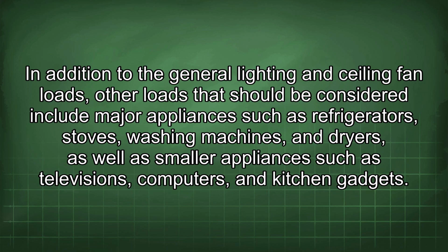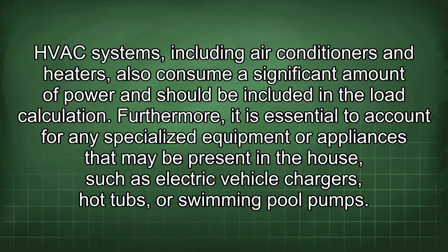the house. In addition to the general lighting and ceiling fan loads, other loads that should be considered include major appliances such as refrigerators, stoves, washing machines, and dryers, as well as smaller appliances such as televisions, computers, and kitchen gadgets. HVAC systems, including air conditioners and heaters, also consume a significant amount of power and should be included in the load calculation. Furthermore, it is essential to account for any specialized equipment or appliances that may be present in the house, such as electric vehicle chargers, hot tubs, or swimming pool pumps.